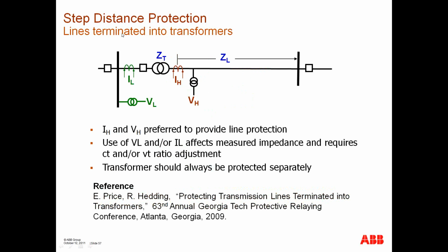And then we talked previously about lines terminated into transformers. And here the issue is that you would always like to use this current transformer and this voltage and do protection for this line, and always do separate transformer protection.